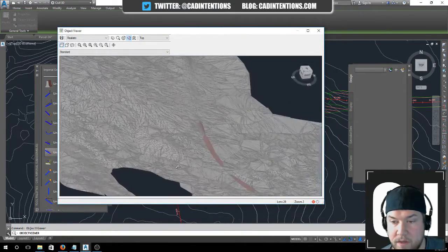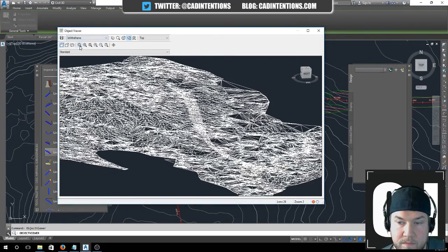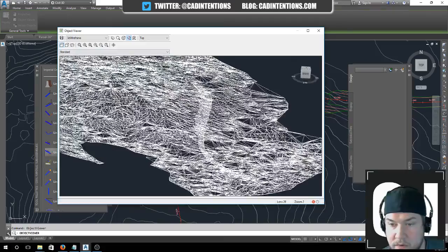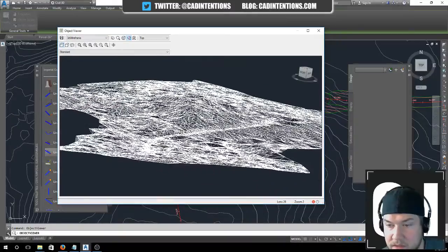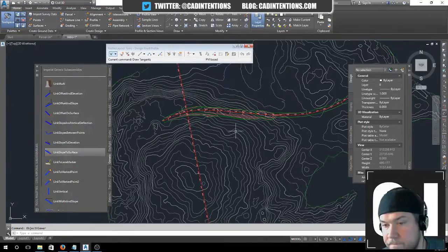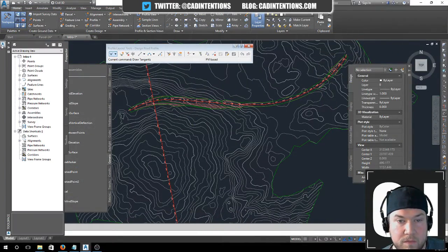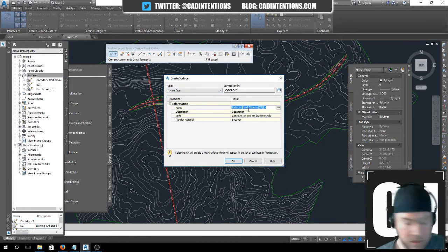Your road coming through here. Now quickly, I designed a road that goes in and through the little hill here. What we can do to better show it is create a paste surface, paste the two together, and then you'll see what our final surface would look like.